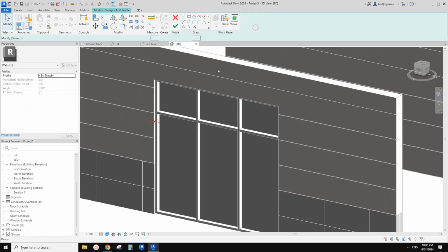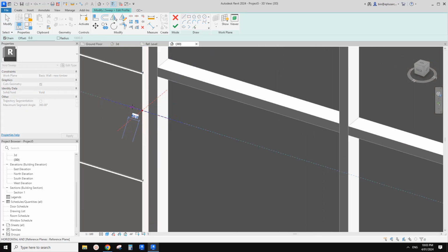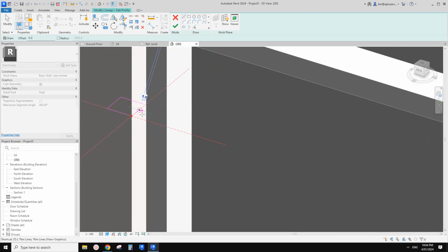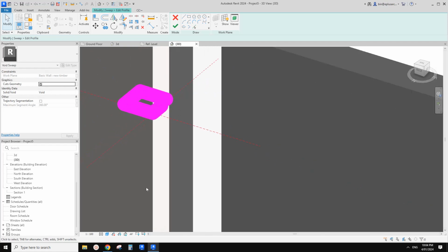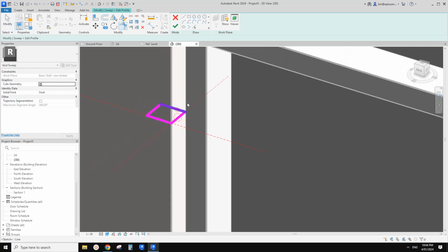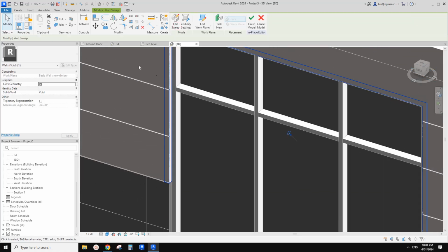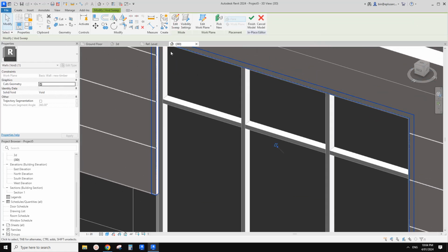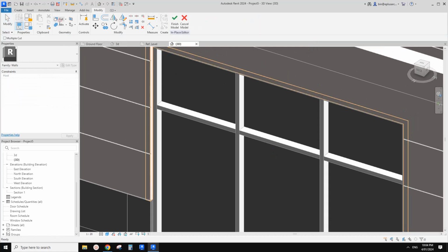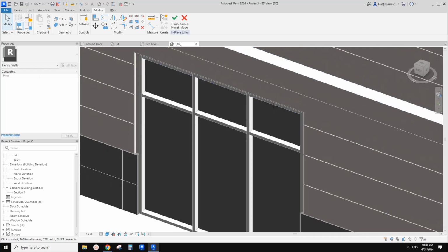Now we can create a profile. Maybe let's make it 50 by 50 or 60 by 60, and then just a square. Oops, sorry. Let me type TL. That's too thick. Maybe 120. Yeah, that's better. TL. So that's a square shape profile, and then we can finish this void. Before we click finish model, we can use cut geometry, click on the wall, click on the void. So this will create a void for us.